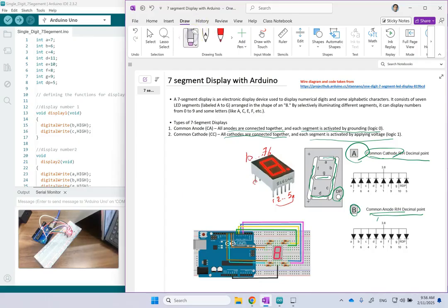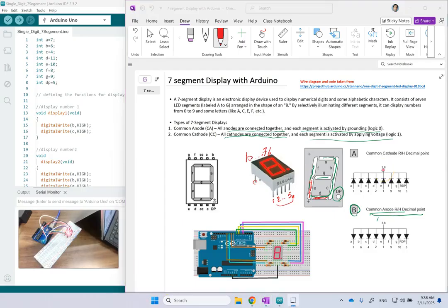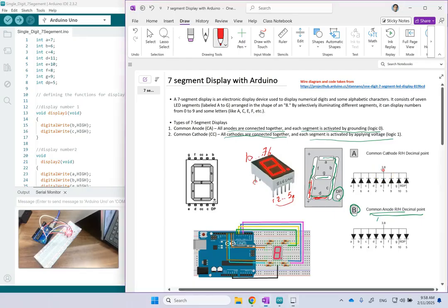If you look at this wiring diagram, you can see that for common cathode, which is the one we have, pin 1 is going to turn on LED E. So when you go 1, it is going to turn this one on. When you go 2, that's D. When you go 3, you see that 3 here, that is the ground, right? The same goes for pin 8.